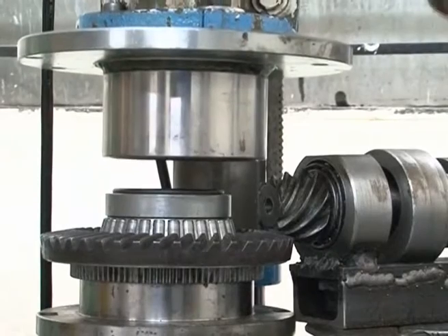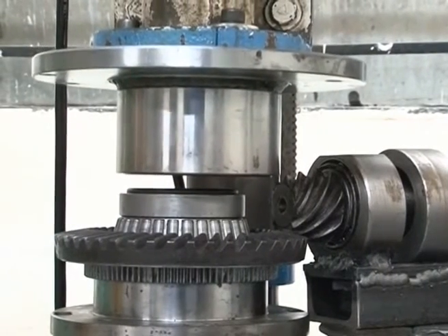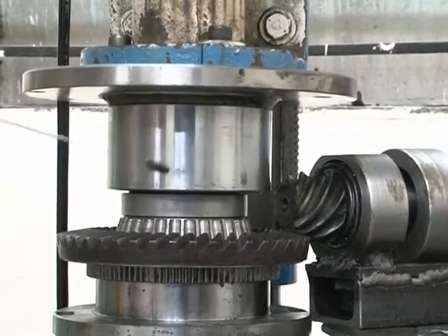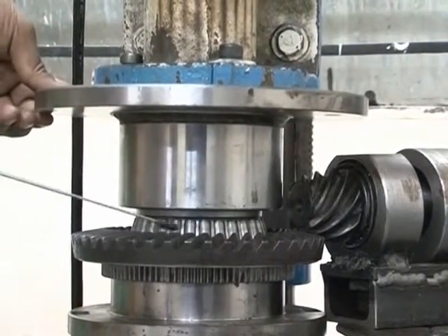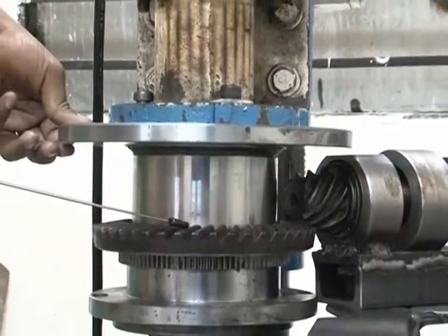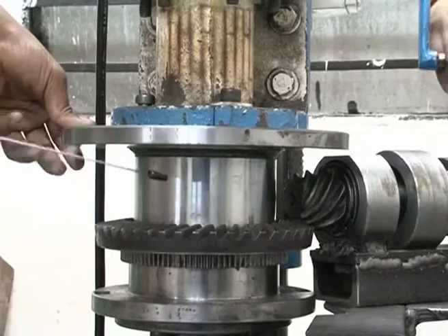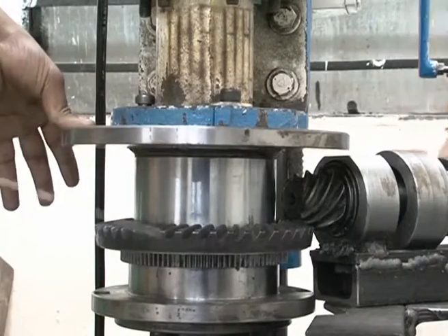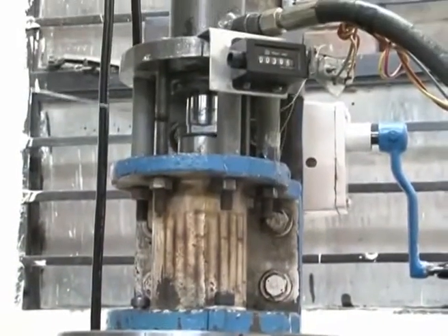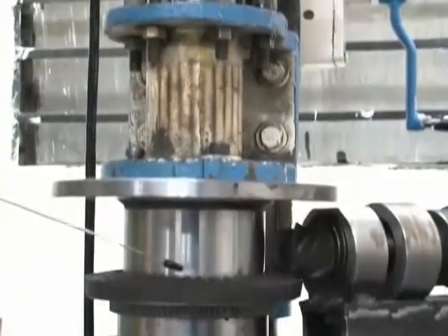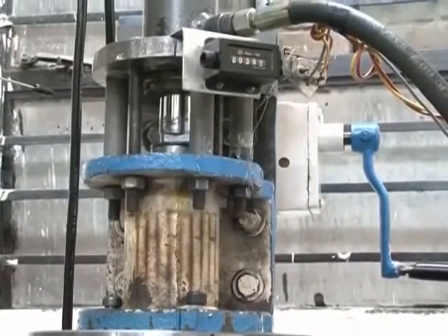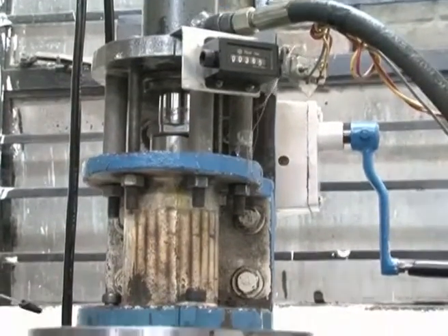Now you can see the complete tooling that is sitting on the rotational tooling. This is the top plate that covers the external rotational tooling, and this is the bottom plate wherein the external tooling is already existing. In this way the complete tooling is mounted. Once both motions are given, reciprocation motion to the medium as well as the rotational motion to the workpiece, this is how the rotational abrasive flow finishing setup runs.